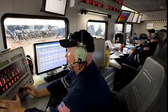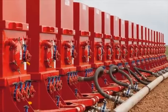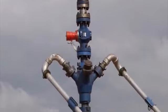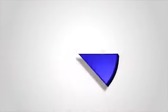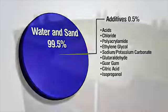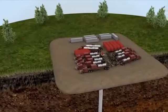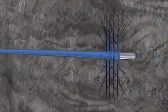The process consists of pumping a mixture of mostly water and sand, plus a few chemicals, under controlled conditions into deep underground reservoir formations. The chemicals are generally for lubrication, to keep bacteria from forming, and to help carry the sand. These chemicals typically range in concentrations from 0.1 to 0.5% by volume and help to improve the performance of the stimulation. This stimulation fluid is sent to trucks that pump the fluid into the wellbore and out through the perforations that were noted earlier. This process creates fractures in the oil and gas reservoir rock.